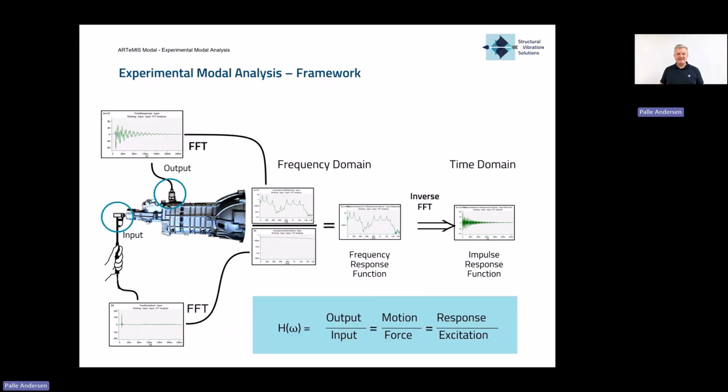Again, a little schematically, how do we actually do it? If we're doing something we call impact testing, which is a very typical way of testing smaller structures, then you can imagine we have a structure that we have mounted in some test rig so that it's isolated from everything else.